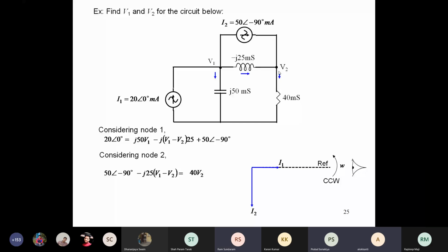Okay. The node 2 equation and node 1 equation. So now you have to solve this. Again, a complex solution of V1 and V2 is required, where the coefficients of V1 and V2 will be complex, and the solution has to be found out. So what is the solution? Is the V1 angle 23.3 degree? Which one? In V1, magnitude? 1.062, 1.061. So solving the above equations, you basically get this.